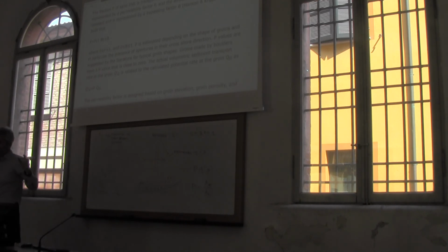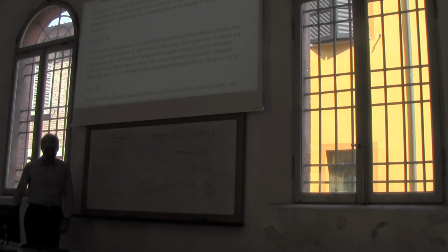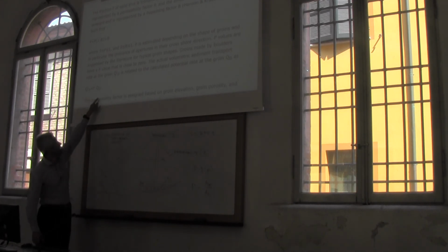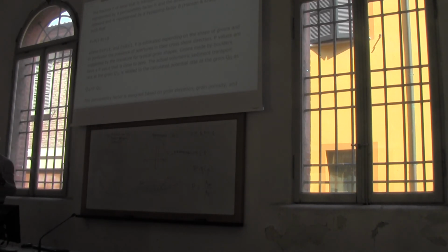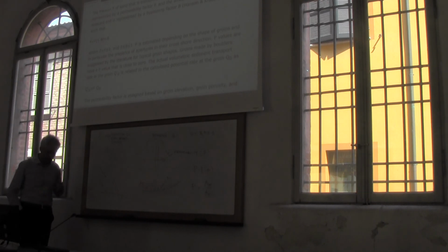It's a very simple formula, but I want to dedicate some time because it's not immediate to understand. Once you have the F value, you just correct the longshore sediment transport with this relationship. In the model, you remember that by knowing the energy of waves we compute the longshore sediment transport. Once we computed it, we reduce it according to the presence of the structure.